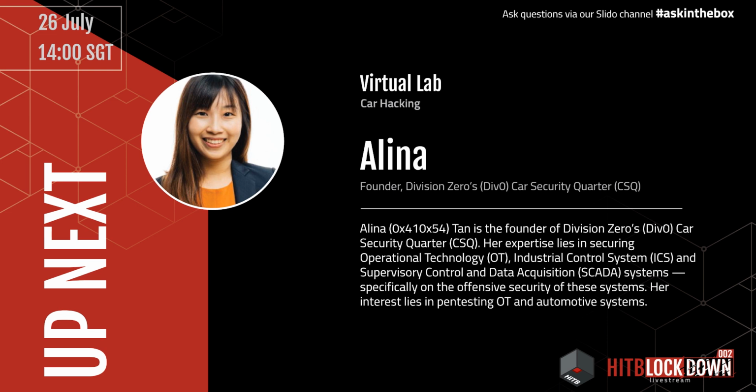And also in ECUs, you have something called HSMs, your hardware security modules. It's sort of like encryption to prevent the ECU from getting hacked as well. And even in UDS, the security access session itself is not that easy to break into. So fundamentally, yes, there are security measures, even though it's not as advanced as compared to computers.